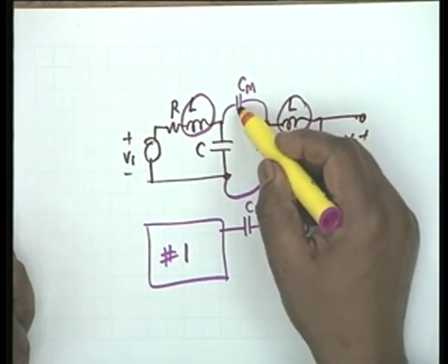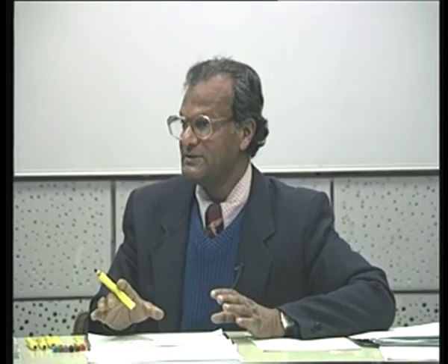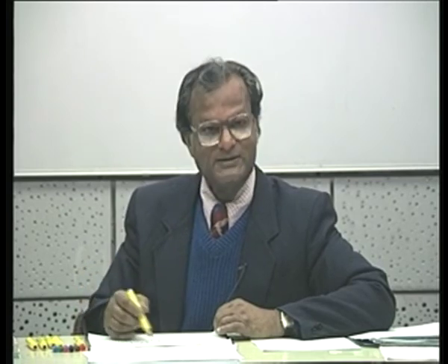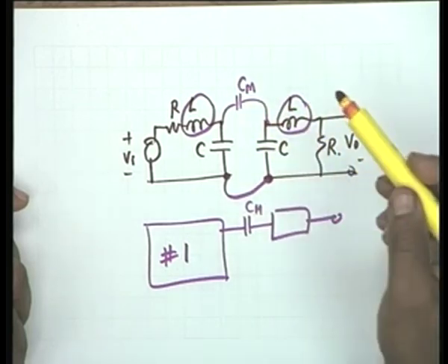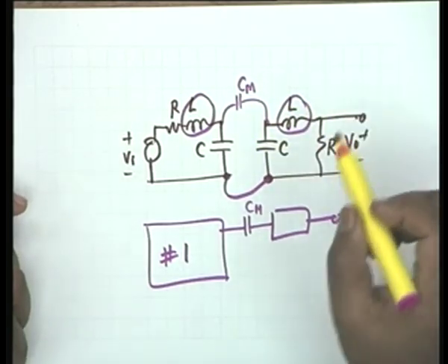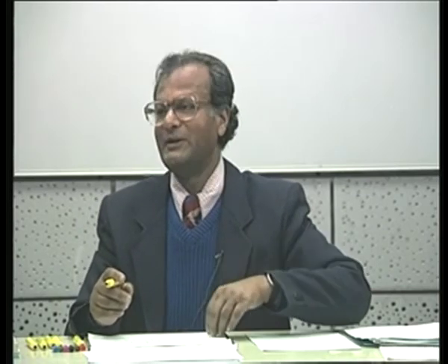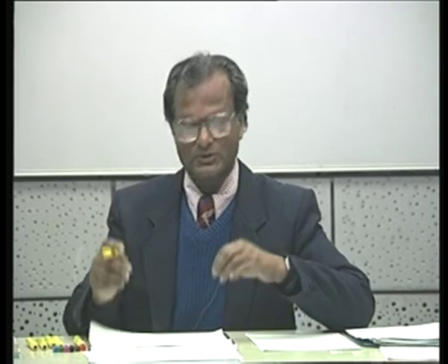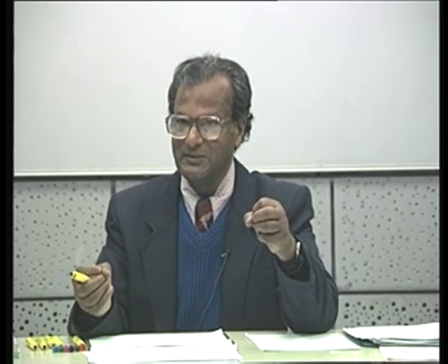If Cm is 0, there is no coupling. This is called capacitive coupling, instead of inductive coupling. If there is a non-zero Cm, then you shall observe exactly the same kind of behavior as in a double tuned circuit. So two tuned circuits can be coupled by capacitance also.